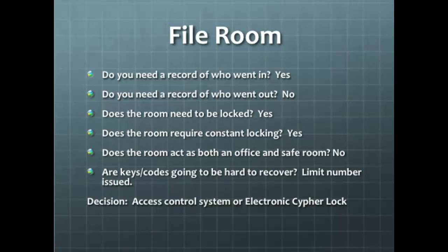I think when you're talking maglocks and electric strikes, if you're not in bad weather, you can use either. Some people like to standardize on the maglock. They don't make a noise. You don't have to cut the frame as badly. I used a strike, but again, your choice. But in this case, because you need a record, you need a history, automatically all of those mechanical locks came off the table and you were stuck with either the electronic access control or an electronic cipher lock. I went with access control, I think the cleaner option, because it's less work when people leave.